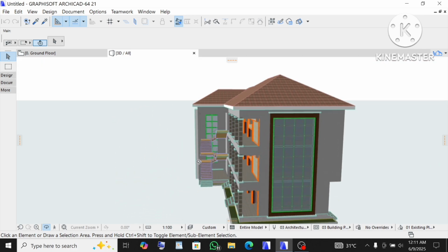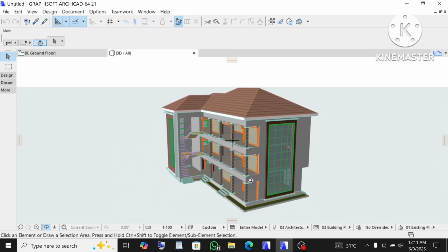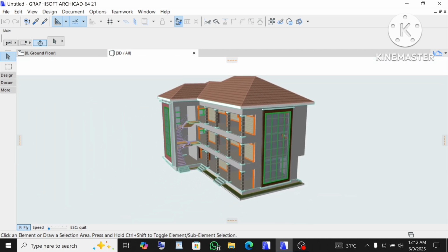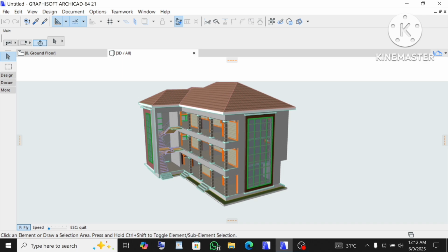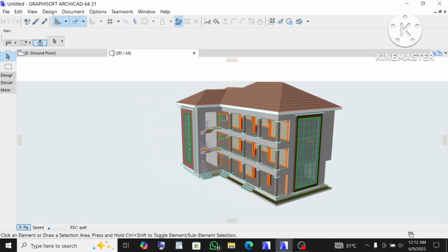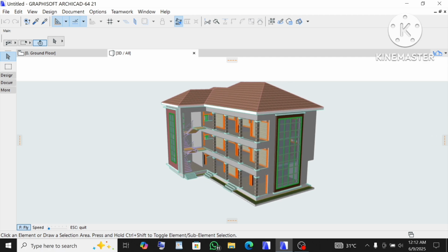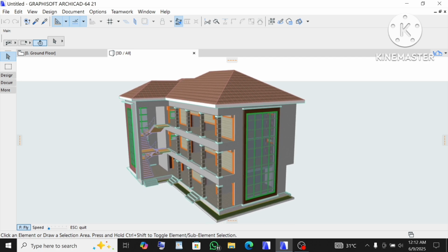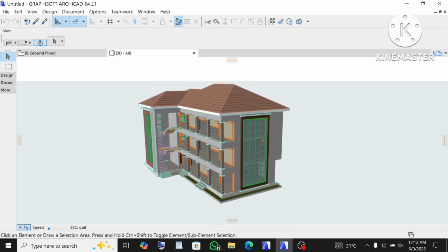Alright. Now there is also an explore mode. I also call it a game mode, which is right here. You can see this explore. When I click on it, I will move my mouse. You can see how the building is moving, and I can also control this building by using four keys on the keyboard: the W key, S key, A and D keys. For the A key, I will go to the left. You can see that I can go to the left with my A key, and as for the D key, I'll go to the right. For the W key, I will move closer to the building, and for the S key, I will move away from the building. So that's how to do that.